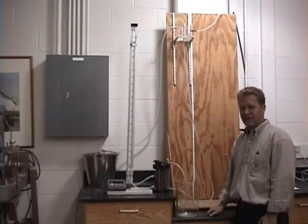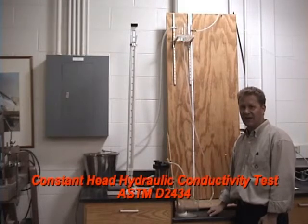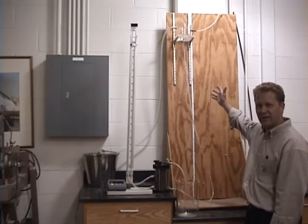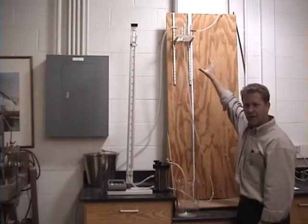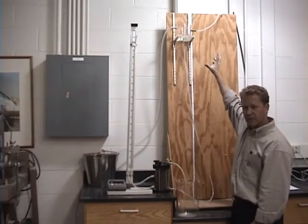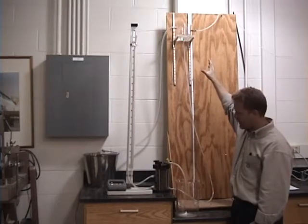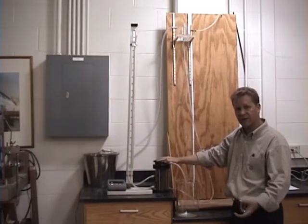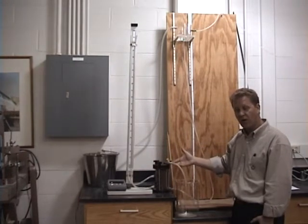This demonstration is measurement of hydraulic conductivity in granular material using the constant head method, ASTM D2434. The configuration is shown here. The test configuration that we're going to use consists of a few parts. First part is the reservoir that we're going to maintain filled with water at a constant level to maintain a constant head. We have a permeameter here full of some granular material, some sand. We're going to flow water through this sand and measure the flow rate.